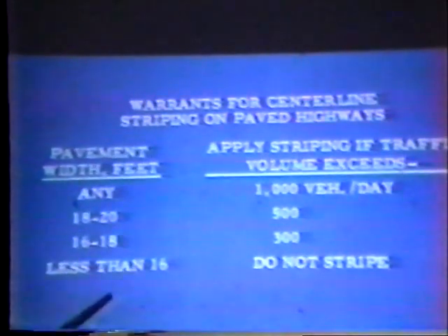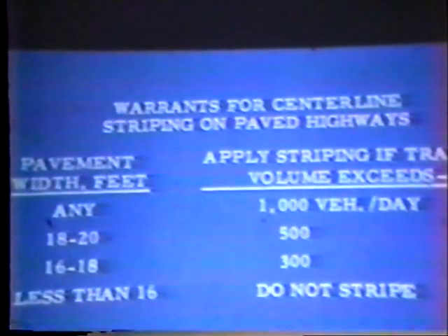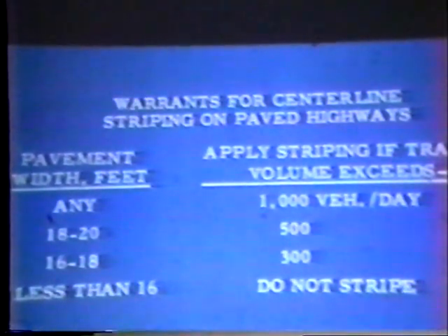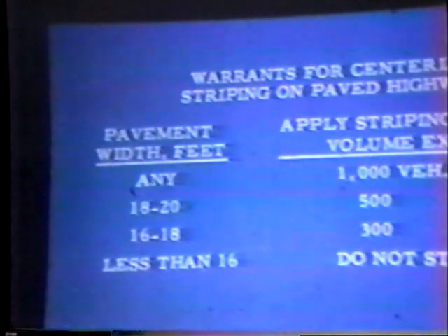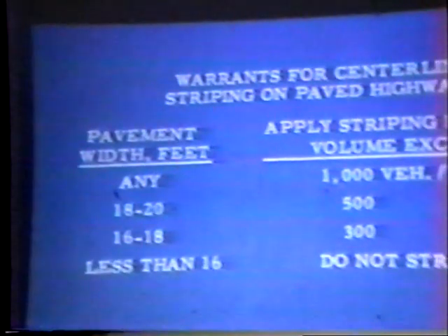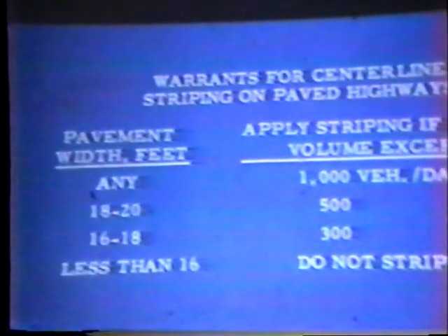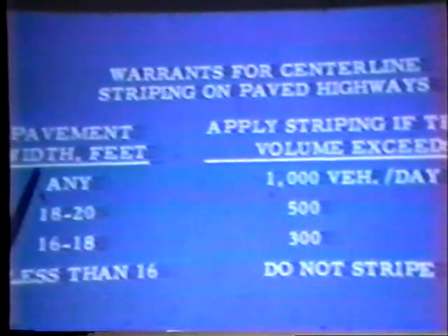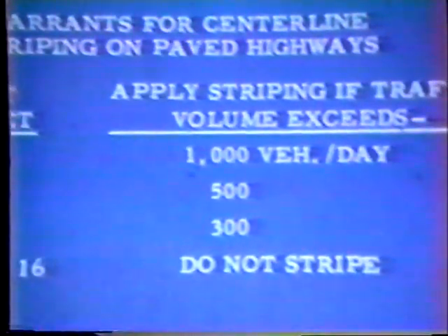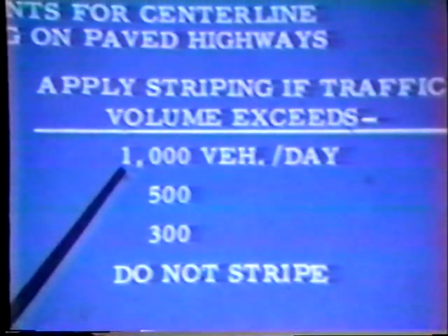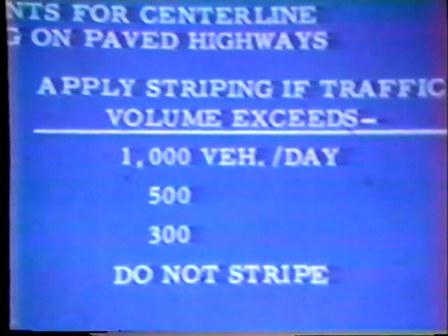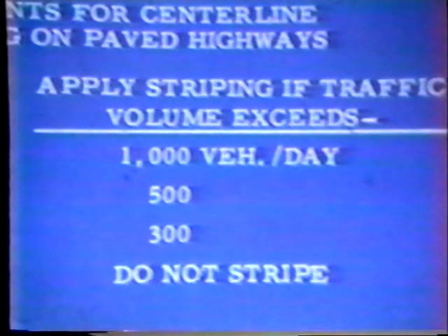Center line striping is another consideration, and believe it or not, and this comes directly out of the standards of the American Association of State Highway Officials, there are some circumstances under which the recommendation is don't put a line down the middle of the road. You probably would expect me to tell you that you should always put a line down. That isn't the case. When you have relatively wide roads, or regardless of the width of the road, but relatively high traffic, you should apply a center line stripe.